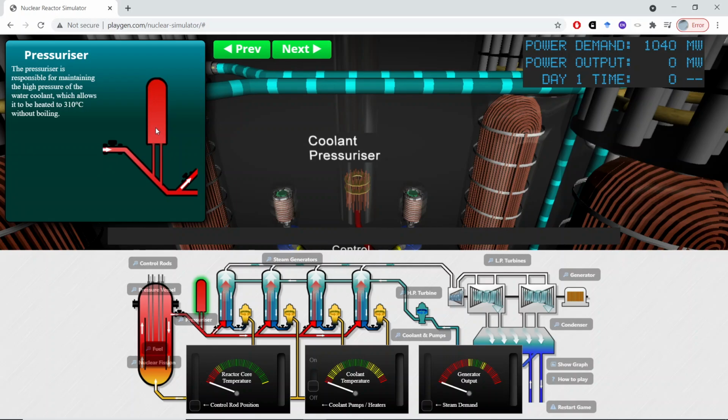And what do you do if you want to reduce, because of some reason, pressure in the reactor very quickly? You open the shower in the top, and because you are making cold water rain in hot steam, the hot steam will condense very quickly by reducing a lot its volume, and this will automatically reduce the pressure in the primary circuit.